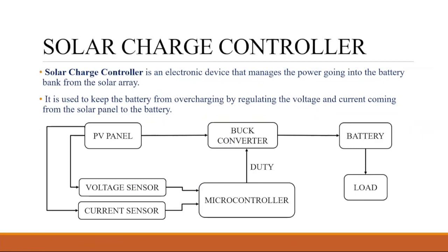Do you know what a buck converter is? Yes, DC to DC. Is a buck converter step up? No, step down. That is boost. Boost means it will boost. Buck means it will cut down. So basically, a buck converter is a DC-DC converter which lowers the DC voltage, or cuts down the DC voltage. Okay. So I will draw the circuit of the buck converter.